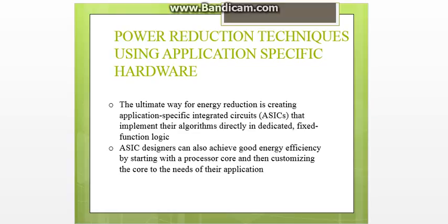Next are the techniques using application specific hardware. The ultimate way for energy reduction is creating application specific integrated circuits that implement their algorithm directly in dedicated fixed function logic. ASIC designers can also achieve good energy efficiency by starting with a processor core and then customizing the core to the needs of their application.